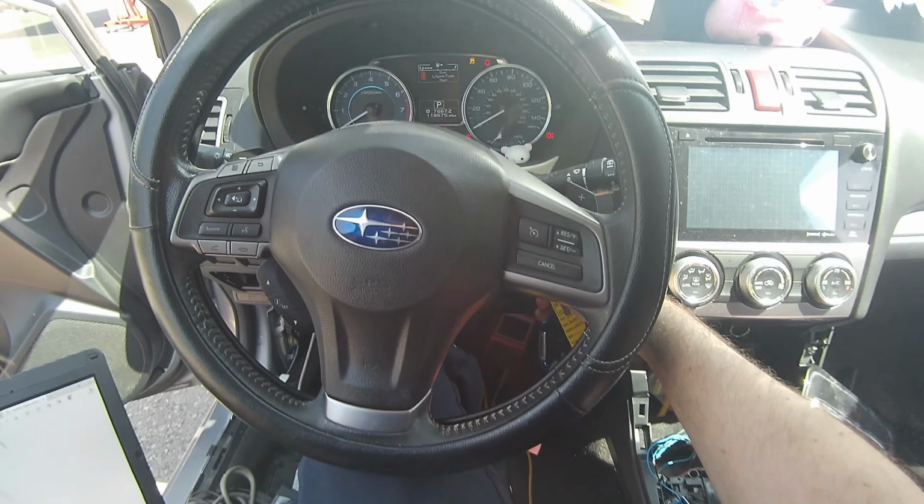So it looks like the BIU is going to be controlling the power, and it's going to put out power to this coil which is going to energize the switch. I can test that really simple. Okay, so let's go to pin 3. Pin 3 of that connector.